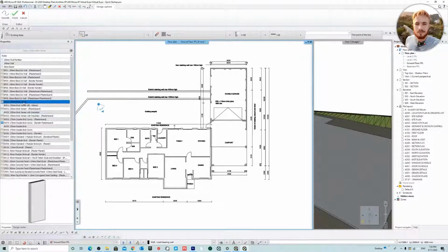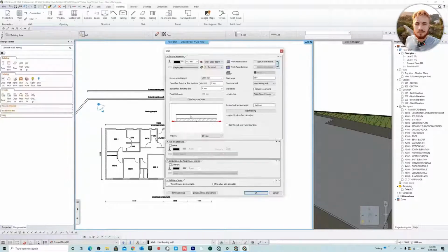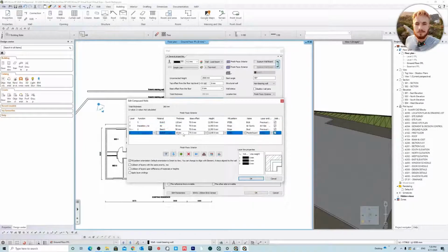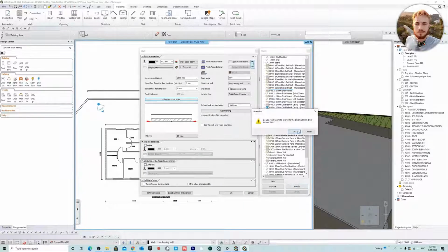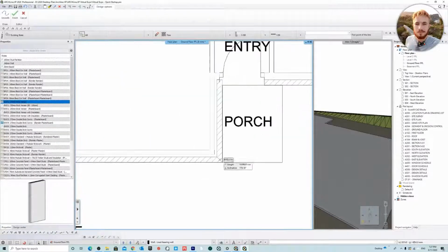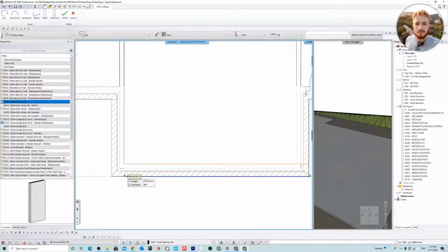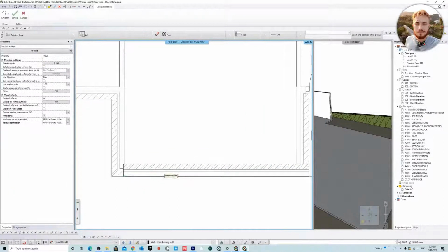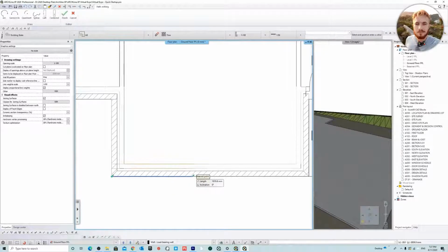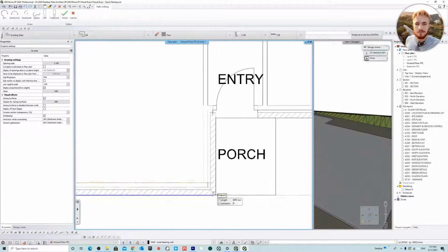So we've got the brick veneer. I'm just going to right click to properties and remove this plasterboard layer. Then we'll go modify and activate, and then we can start placing this. We'll go from right to left. We'll hit F5, and okay, wrong way around, so we'll go left to right. F5, and we can just hold shift and it'll snap here.